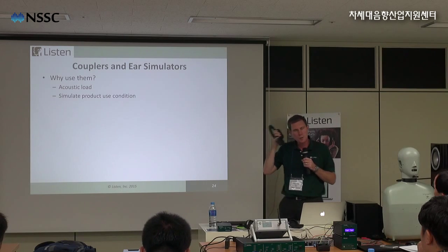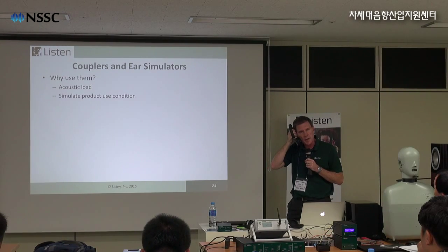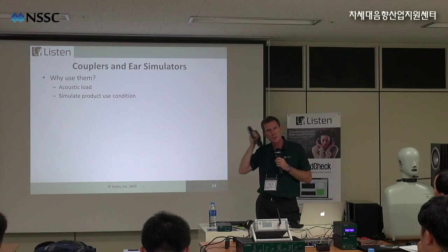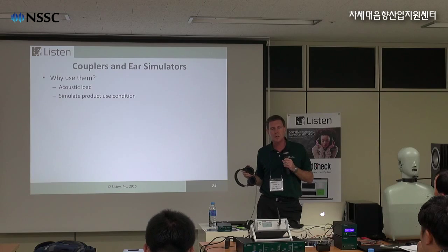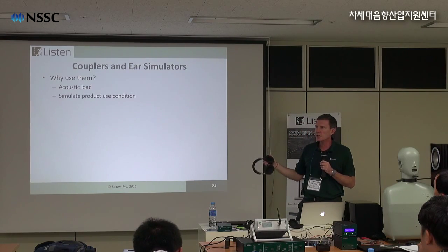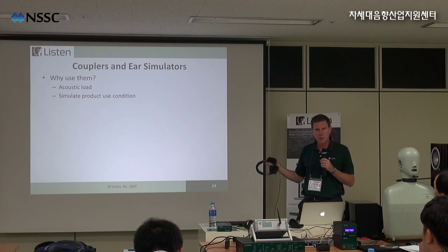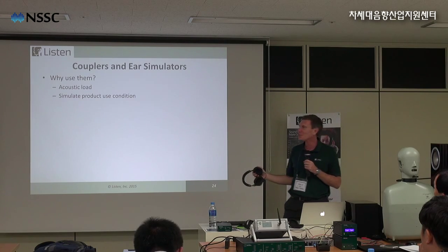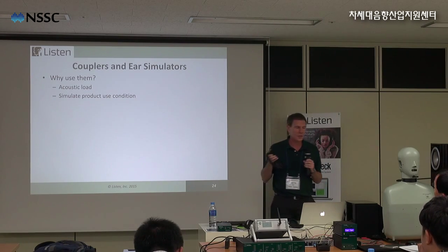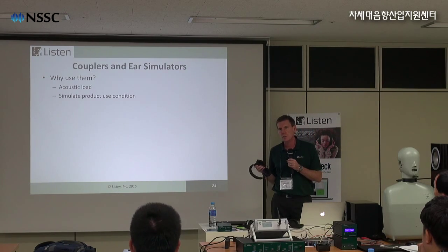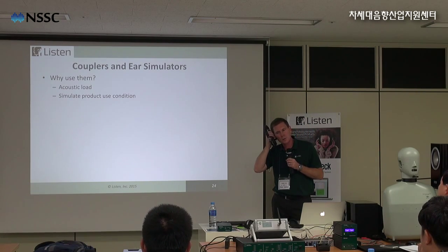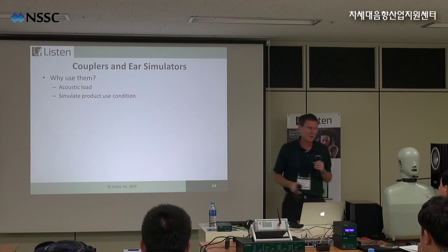But the moment I put this over my ear, I now have a closed coupling between my ear and the headphones, and all of a sudden I can hear a lot of bass. So really, if I were to try to measure these like a normal loudspeaker, they would look terrible. There would be no low frequency information. So we've got to simulate that. And different headphones have different acoustical impedances. This has a different acoustical impedance than an open ear headphone typically.